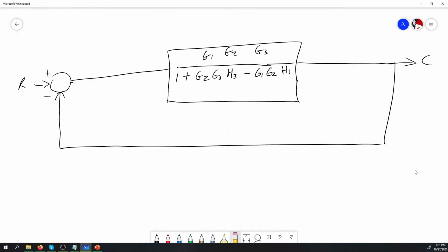So at this point, when we reach here, we see this is negative feedback. So the standard transfer function would follow such as it's G over 1 plus GH. Now, the feed-forward path, we know this here is going to be our G block. But the feedback path there, we just see it's going to be just a line. And when you have a path which is just a line and there's no block, that means the block value associated with this line is just going to be 1. So in this particular case, H here is just going to be equal to 1.